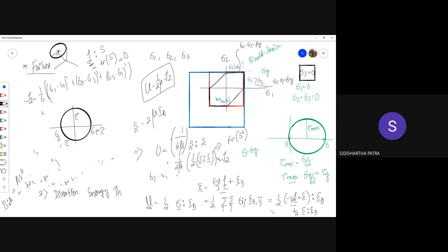So if I substitute in this expression, it is going to be 1 by 6 times 4 tau squared plus tau squared plus tau squared, which is tau squared. And the failure occurs when this tau is tau y, which means U critical is 1 by twice mu tau y squared. And this is the target value, the target value for the distortion energy when the failure must occur.